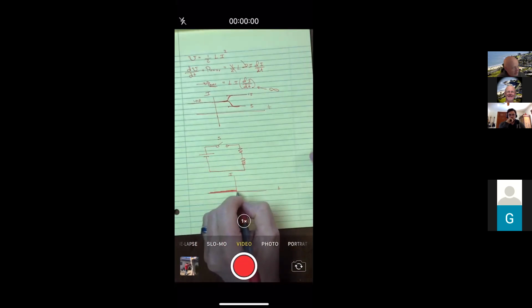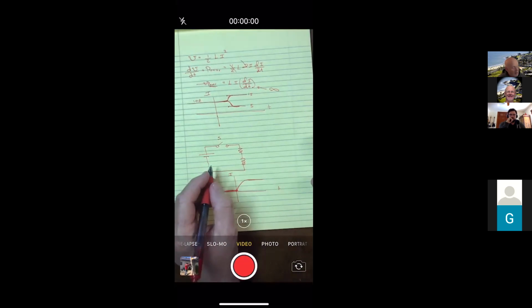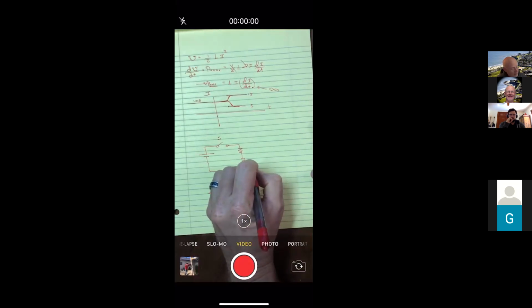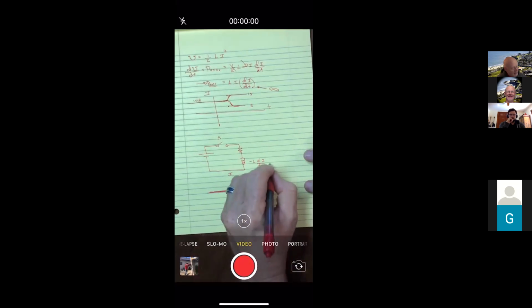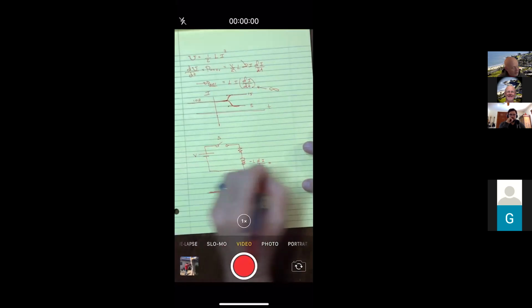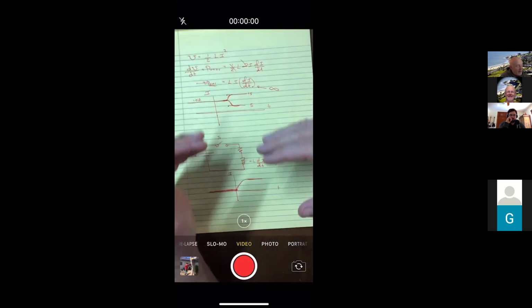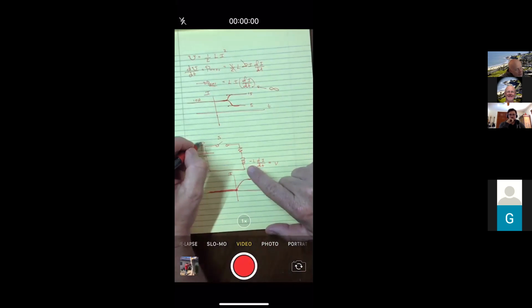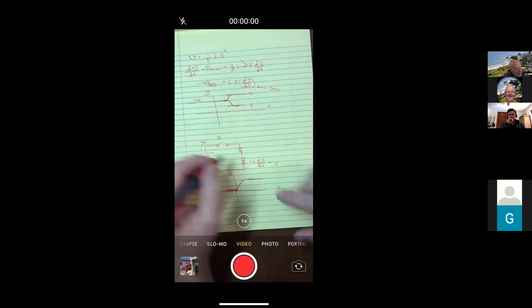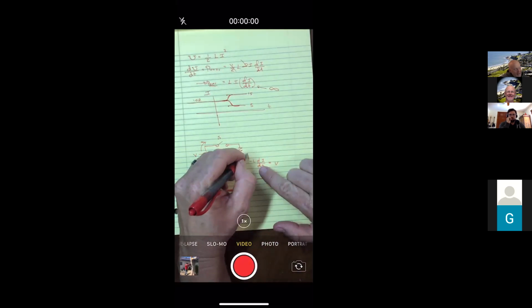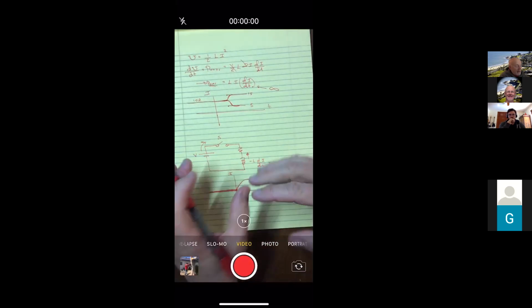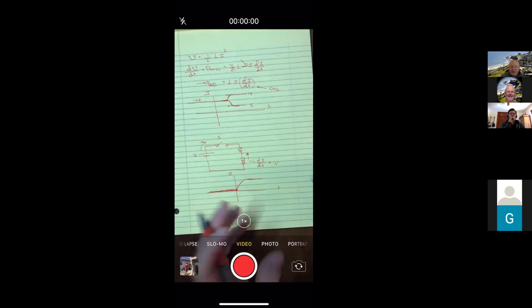Then when you close the switch, sure, it will build up to some maximum value, but immediately when you close it, it's got to be 0. And that means, as you said, there would be a back EMF created that would equal the voltage of this battery. So when you first close it, this battery is trying to put current this way, and this inductor creates a back EMF of the same voltage, and that leaves the current at 0, at least for that moment.